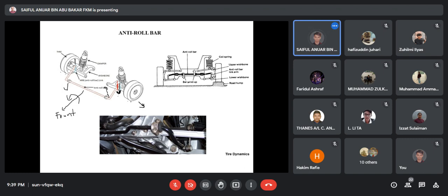It's the same here. This is the drop link, the attachment point for your anti-roll bar. Same thing. Any questions about this anti-roll bar? Basically, if you use a standard anti-roll bar from the manufacturer, it usually works well at the beginning, and then eventually over time the performance is reduced because of this bushing. If you take a look at this one, this is actually a bushing.